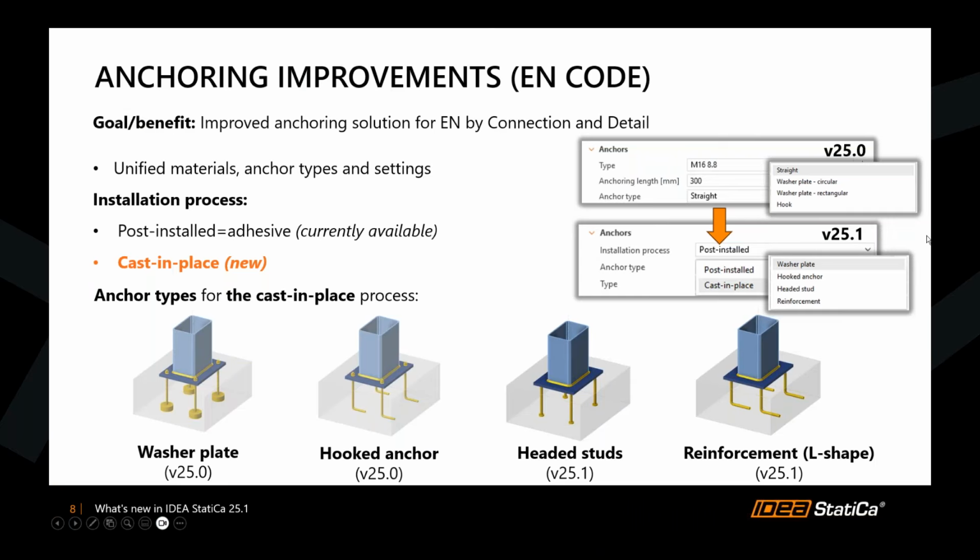First of all, we are trying to do unification between these two software, steel Connection and concrete Detail. We are trying to unify the materials, the anchor types, and of course also the settings. If you have tried upgrading to version 25.1, you will see that there's now an option to choose the installation process, which is post-installed or cast-in place. The post-installed adhesive has been available since version 25.0, but now in cast-in place we have several new anchors.